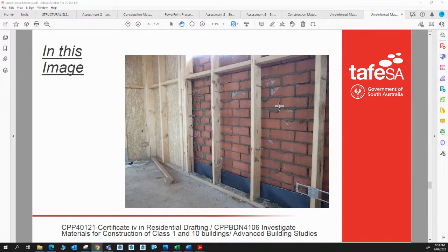What bricklayers do have to do, however, is keep this cavity free of any mortar dags and things like that that would transfer moisture to the frame. And that's why we have a 40mm cavity within the walls. Excuse me there. Yeah, and so that 40mm cavity is there to ensure that we don't get any transfer of moisture from that brickwork through to the frame. And then also these ties have a drip groove in them as well, to ensure that any moisture that's making its way through the back of that wall drips down and onto the flashing there as well.